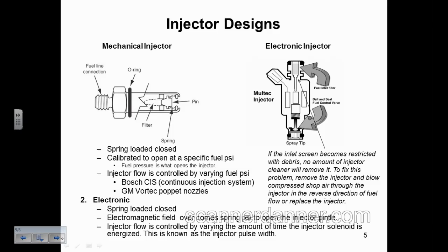So this one here, Matt, you would like this one. You like the Volkswagens. This is actually a German design. This was a Bosch CIS fuel injector. And on a Bosch CIS fuel injector, what you had is an injector that sprayed fuel all the time. The name Continuous Injection System, CIS, boy, it does seem like we're wasting gas, doesn't it? I think this will give you a little bit of perspective on the group-fired system, and that the group-fired system really wasn't wasting fuel either.